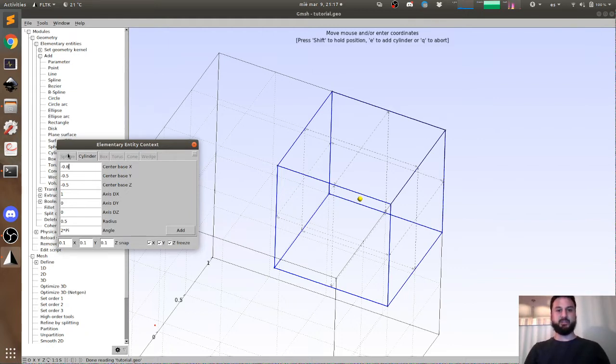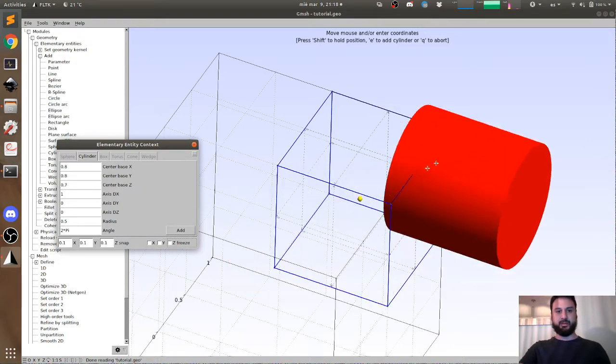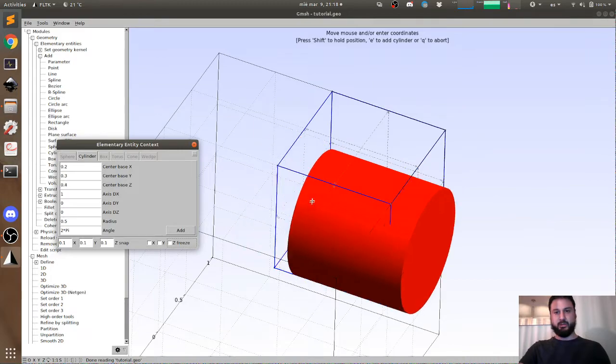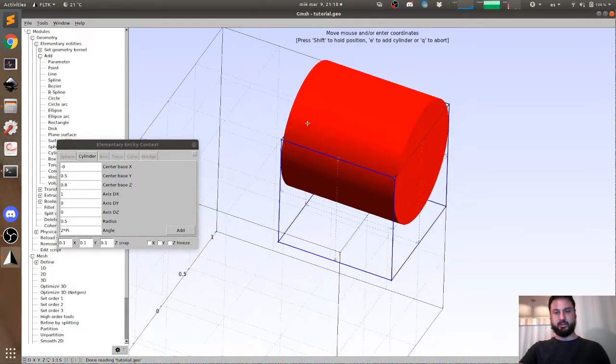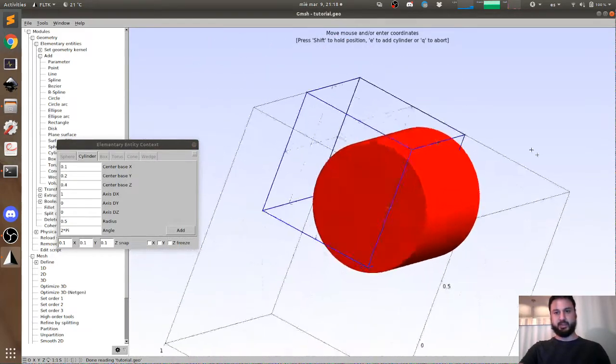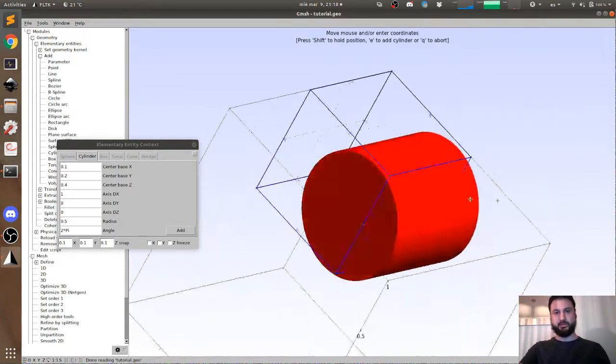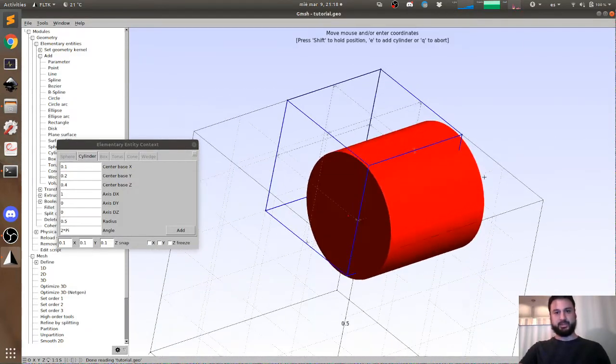That's the basics of it. And then you can do operations like scaling and extruding and rotating and those kinds of things to get more complex objects. So it's a very powerful method of generating 3D objects. So you'll find that your cylinder in this case is aligned with the X direction, which is what I want right now. I can align it in any direction I want.